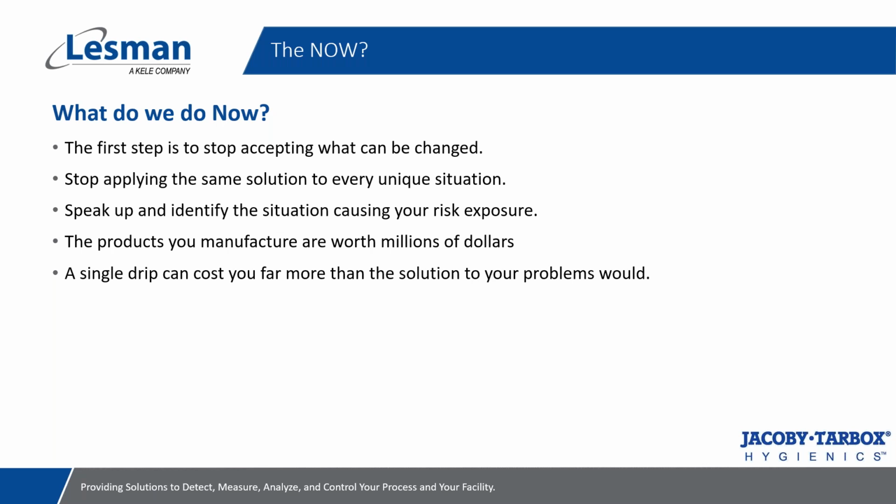Do I have an elastomer that just can't handle the steam pressures, or it just can't handle the caustics of the CIP solution that I push through that line to clean it? Do I have piping misalignment, or do I have angular ferrule misalignment? Do I have a clamp that can accommodate the tolerances for this connection?